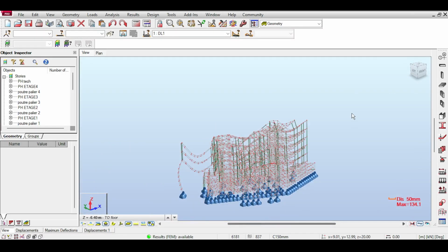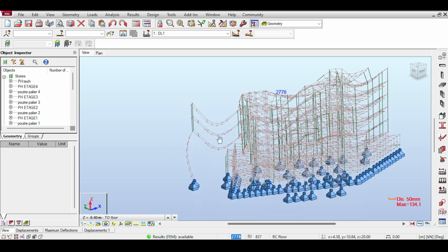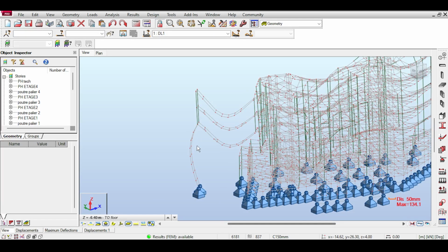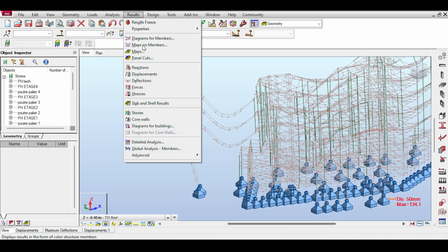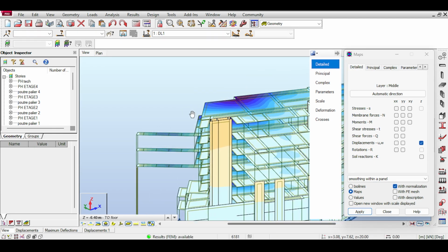Now, this is how you do a deflection evaluation. You do deflection evaluation by looking where the problem places are. There is one problem place. This is because of, I can only say I called it, the stiffness of the shear wall. So, okay, let's go to maps and see the maps because this is kind of not very helping. So I'll just go to Z and click on maps. And let's take a look where the problems are.